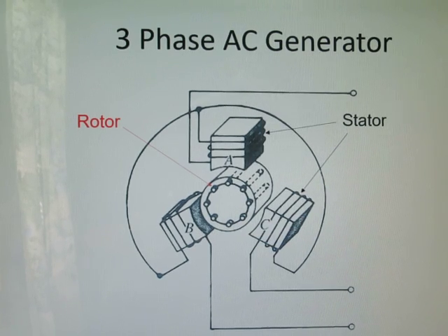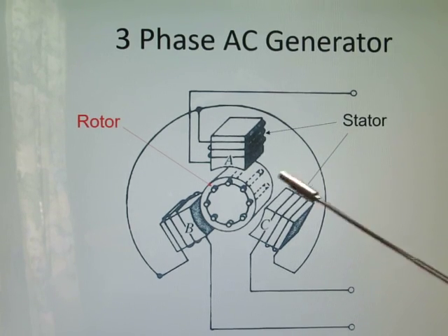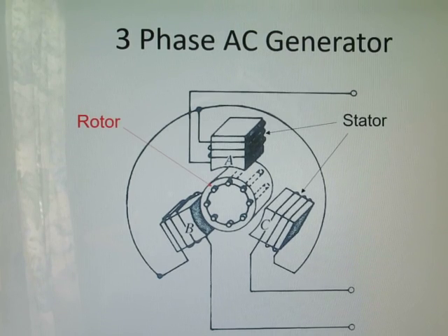And the moving part, the rotor, has the magnetic field source, while the stator contains the conductor where the EMF, electromotive force, is induced. The induced voltage value at the ends of the stator depends on the magnetic field strength, the rate of the field change, and a lot of different functions respective to the design of the AC generator. We're not here to design generators, but we just want to understand at a high level how three-phase voltages are developed.